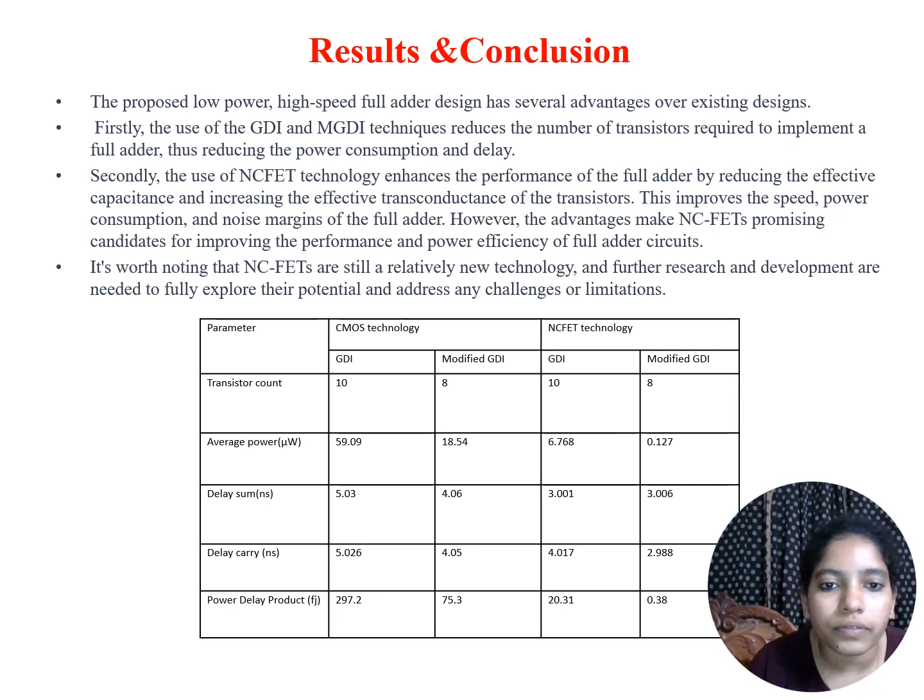These are the results we observed from this implementation. Firstly, with the help of GDI and modified GDI techniques, we focus on the transistor count. By using the GDI and modified GDI techniques, we reduce the transistor count required to implement the full adder, thus reducing the power consumption as well as delay. Secondly, using the NCFET technology enhances the performance of the full adder by reducing the effective capacitance and increasing the effective transconductance of the transistors. And the proposed low power high speed full adder design has several advantages over existing designs.